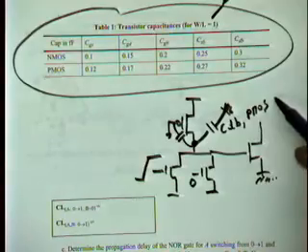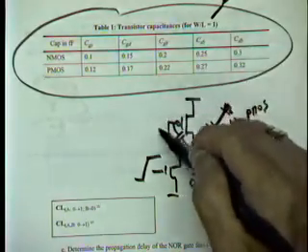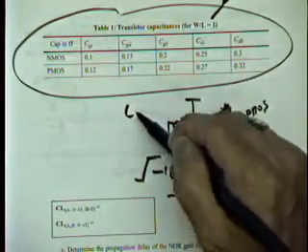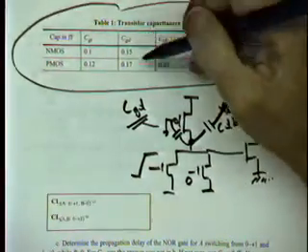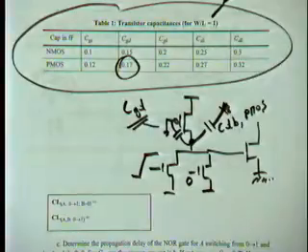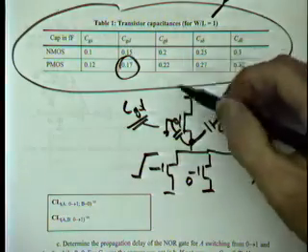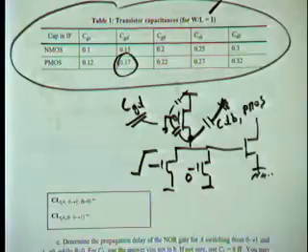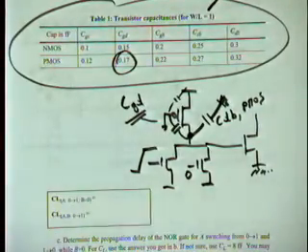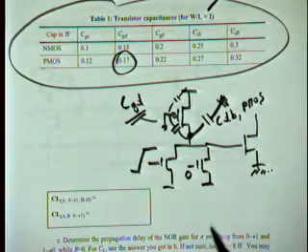So I have to add basically the CGD of your transistor, which in this case for the PMOS is 0.17. And it's a minimum size device, so we know the value. Okay? All right, and that's about it, right? The gate to bulk capacitance doesn't count. So those are the only two PMOS capacitors I have to take into account.